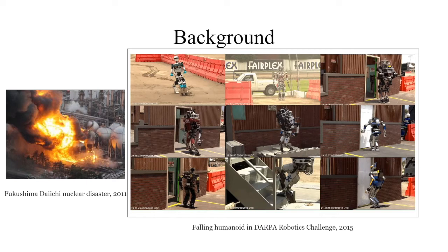Typically, in designing a controller for a humanoid, it should detect the upcoming fall first, then switch from the balanced controller to the fall controller. The fall controller can try to change the direction of the fall, avoid the fall by stepping, or optimize its fall actions to protect itself. However, the foremost and critical part is to predict the fall early enough to allow the fall controller to have ample time to determine the next course of action. This is the topic we will discuss in the following part.